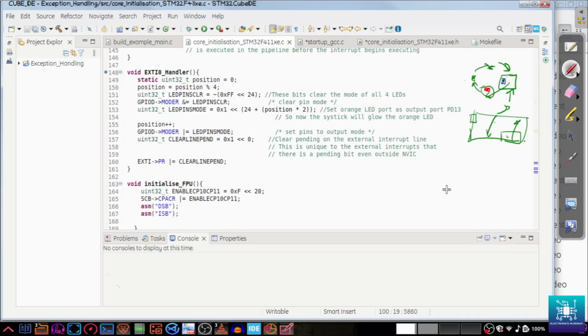And we saw how we actually enabled the LED modes, right? We had enabled the LED modes in some bit fields. So say we enabled the mode here. This interrupt closes this particular LED, it locks these particular bits, and it just shifts the enable bits to the next set of bits. That's all it does, and it keeps doing it in rotation. When it moves to the last bit, it again switches back to the first bit, and that is why you have the percentage operator.